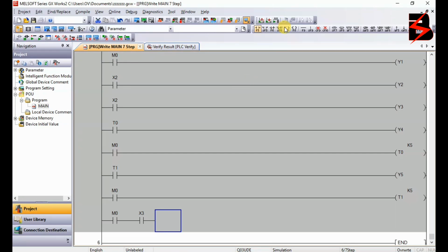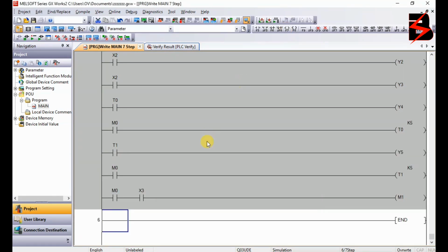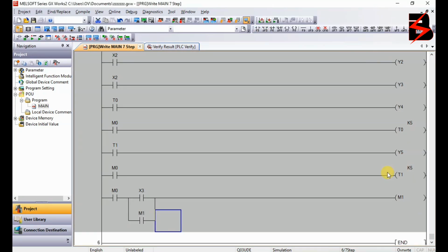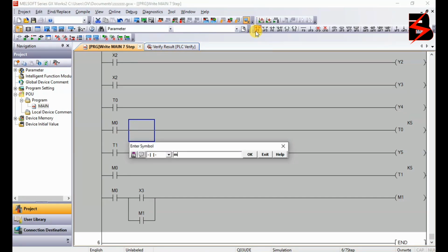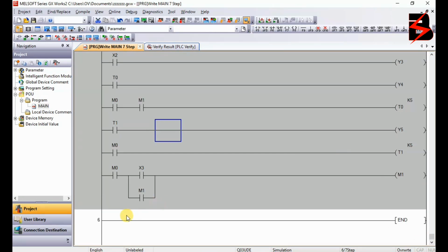Then it's going to power our memory M1. This is now another memory which is going to self-hold itself, M1. Very good. So this M1 is going to clamp the leads here. I'm going to put here normally open of M1. Very good. So we are going to go to clamping the bases on the base conveyor.